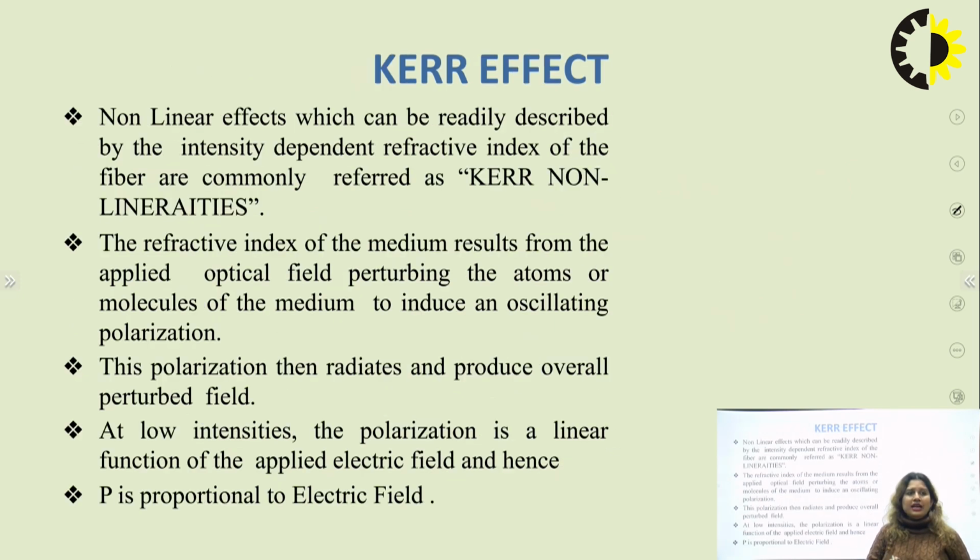So next we have the Kerr effect. The Kerr effect is basically the non-linear effects occurring in the fiber. Whenever you increase the power of the laser beyond some limit, different types of non-linear effects are going to occur in the fiber. These non-linear effects can be easily described by the intensity dependent refractive index, or you can say the refractive index is intensity dependent. They are commonly referred to as Kerr non-linearities.